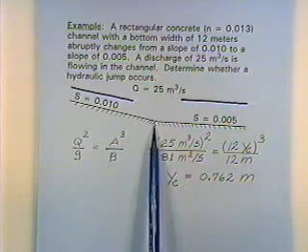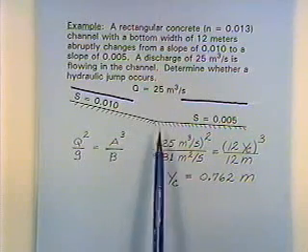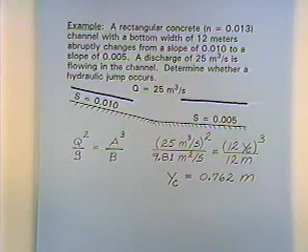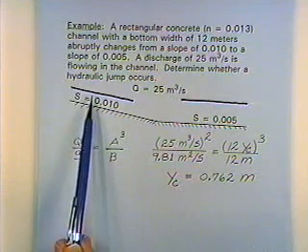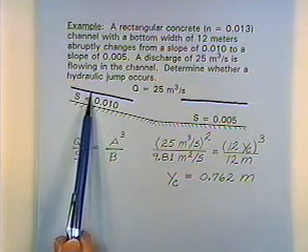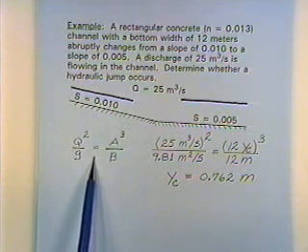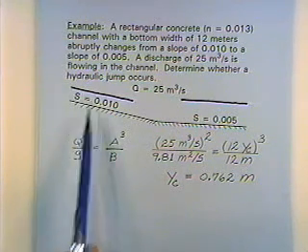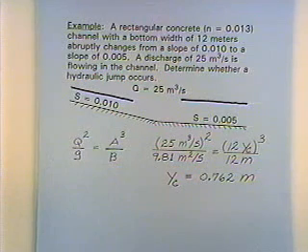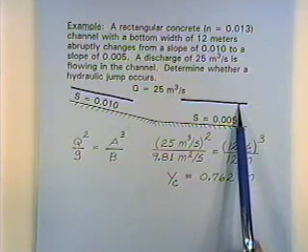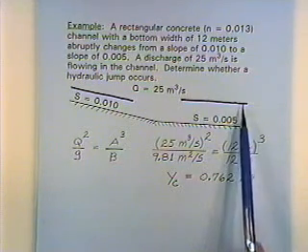And if this is an earth-lined channel, a lot of erosion. And so we want to test that, and there's different ways of doing that. One thing we could do is use Manning's equation to estimate the normal depth here, and then use this equation to estimate the critical depth there, and compare the normal and critical depth to see whether we've got subcritical or supercritical. And then come down here, use Manning's equation to estimate the normal depth.